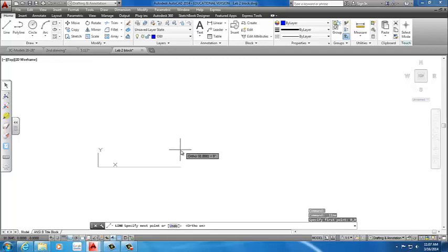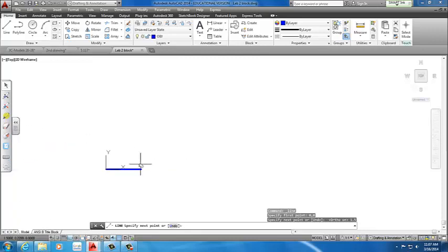We're going to start by going across 1.5, based on the front view of the drawing. You don't need center. I have intersects and perpendicular turned on, and I'm zoomed in pretty good because my drawing was zoomed out too much. That happens. We go up 1, and we go across 1.12. Well, no, the drawing I have, I'm drawing on B-size paper. I got that B-size dimension template by doing a little bit of math.